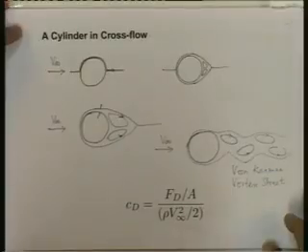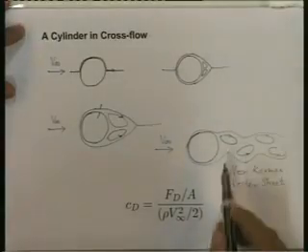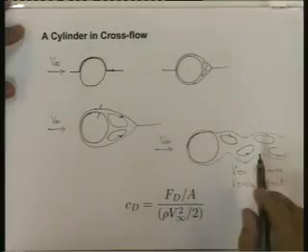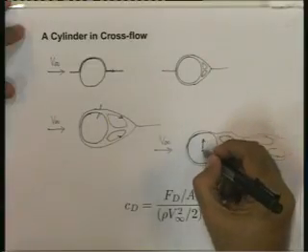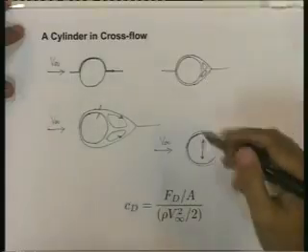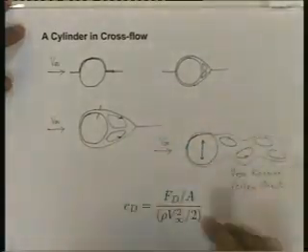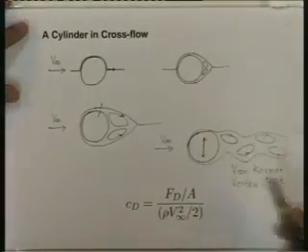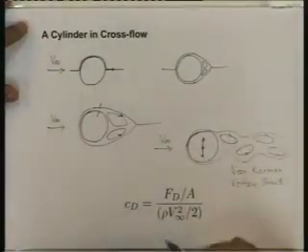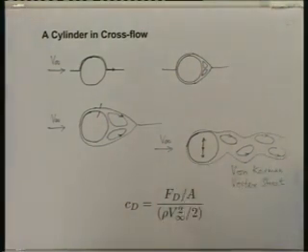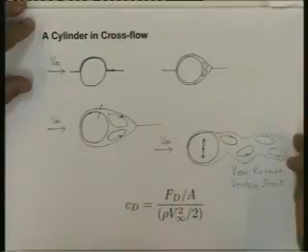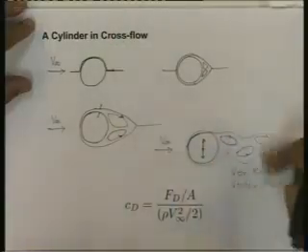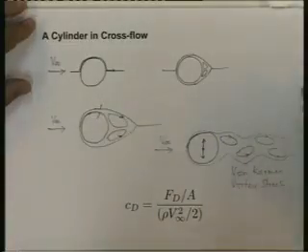This is a very interesting and complicated flow situation, where you have some sort of periodic shedding of eddies. In fact, because of this alternate shedding, a lift force which oscillates in the cross stream direction, perpendicular to the approaching free stream velocity, acts on the cylinder, and if the cylinder is flexible, say a long wire hanging, it will start oscillating, and sometimes you get a nice musical note out of this, a whistling type of note, because this frequency happens to be in the frequencies which we can hear.